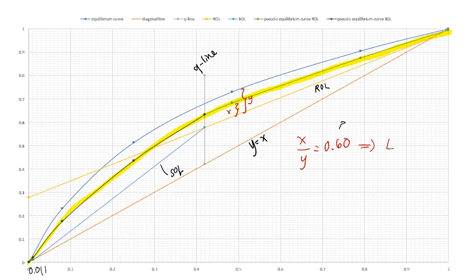That is your Murphree efficiency. Okay, so if you have a nicely drawn line here, you can try to step off the stages starting from XD until XB and calculate what is the ideal number of stages if you step from this line to this line versus if you step from this line to this line. Okay, so you have to do it on your own. Try to do it to actually get it and understand the concept.